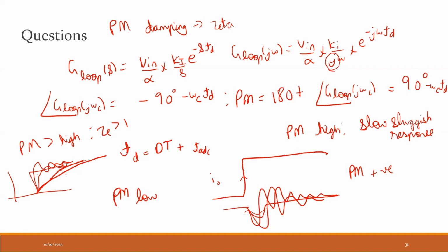Sir, in the S-plane, we keep the poles closer to the real axis, but they have an imaginary value. Is that the response? Yes, if it is underdamped, that means the poles are complex conjugates. That is correct. If you want the oscillation to be less, then the poles have to be closer to the real axis. No, oscillation to be less in the sense means, see, for a second, let us.